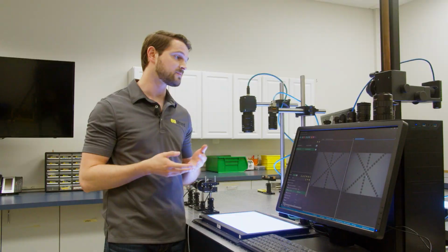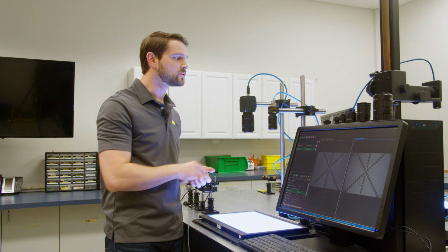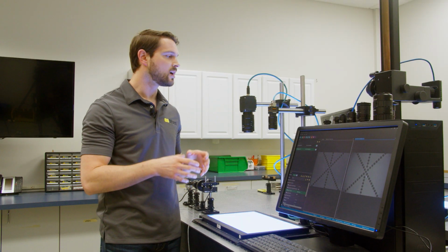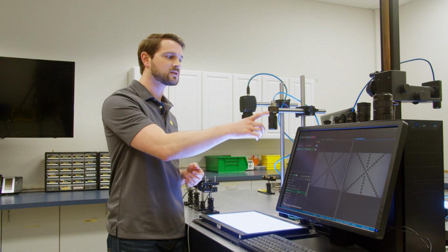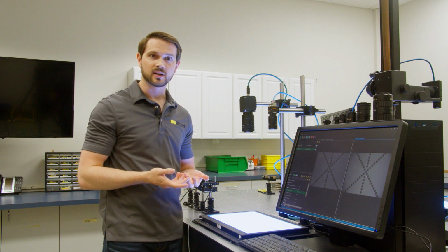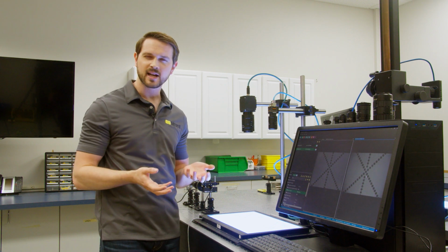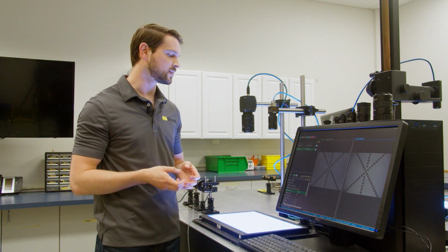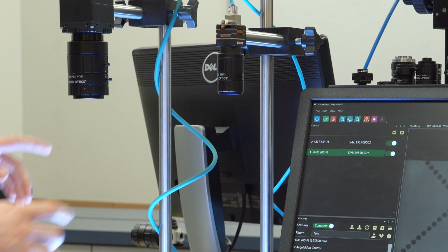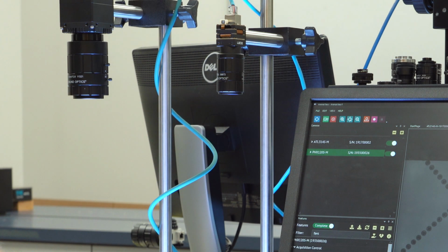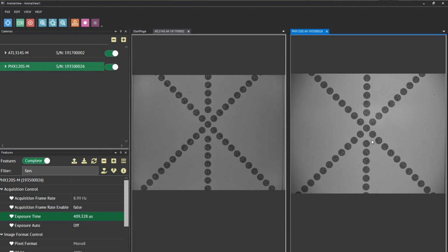So there's a big difference, about a 10 millimeter difference between the two sensors on their diagonals, which means you can cram a whole bunch more pixels, right? We only have 12 million pixels here, and we have 32 million on the larger camera. So what does that actually correspond to from an image side of things? From a lens side, we have a 50 millimeter lens on the 12 megapixel camera, and a 75 millimeter lens on the 32 megapixel camera. The working distances are about the same, maybe a few millimeters different, but functionally the same, and we're looking at the same size field.